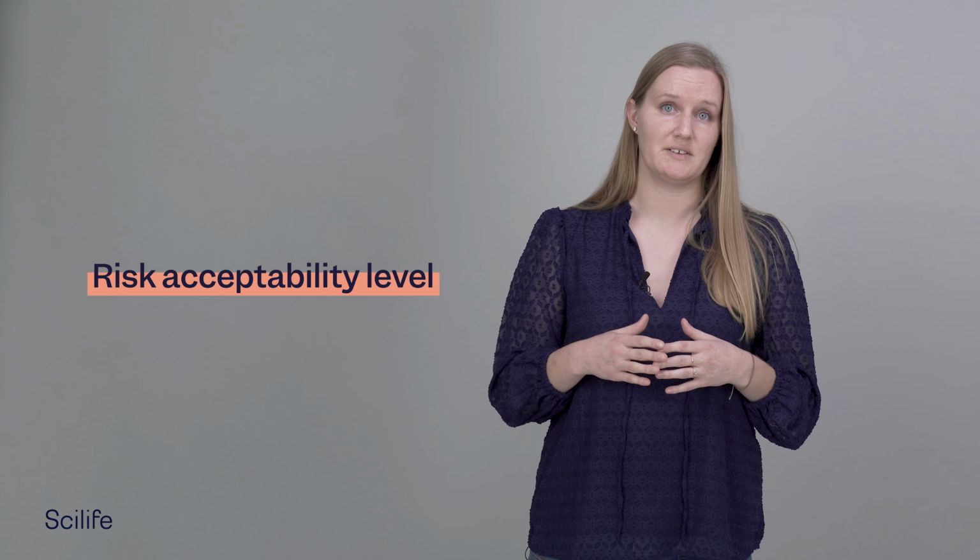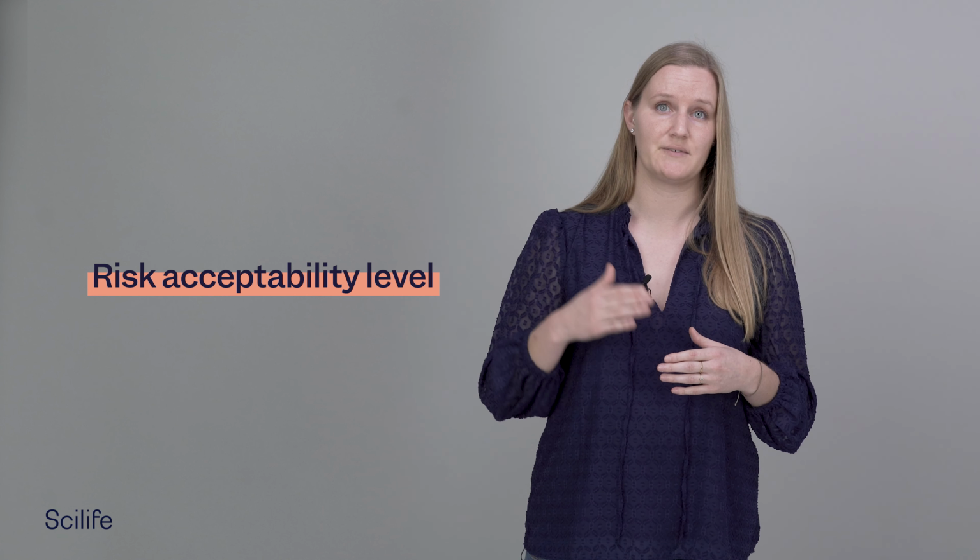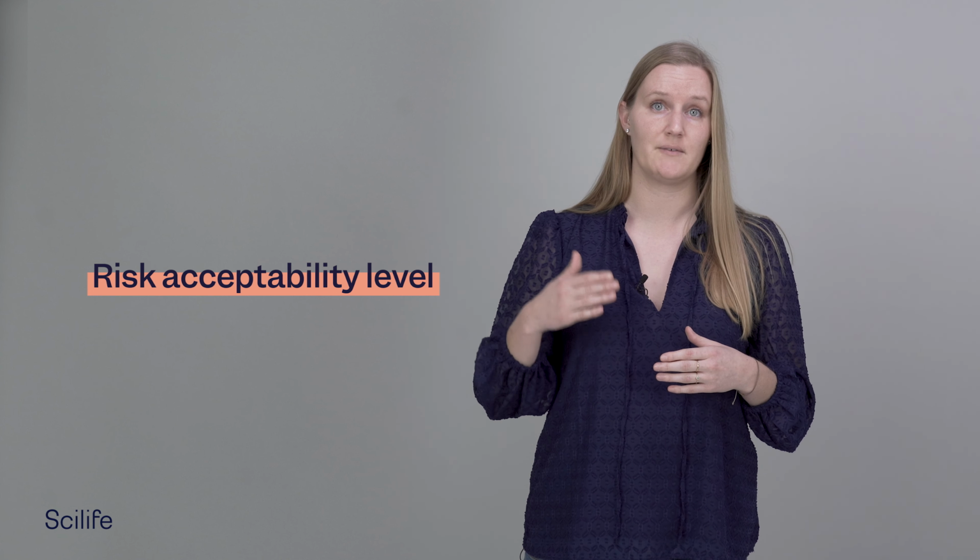The risk acceptability level is the RPN value used as a threshold to determine if the risk of a failure is acceptable. If the RPN obtained is above this value, then corrective actions need to be taken to mitigate or lower the RPN value below the acceptable level. If the resulting RPN is still above the acceptable level, then further improvement and corrective action must continue until the resulting new RPN is at an acceptable level for all potential failure modes.